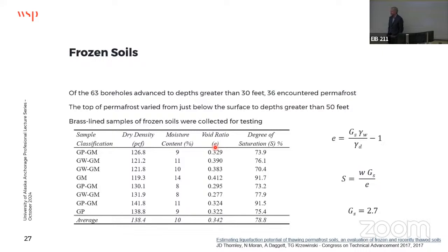So I'm kind of led to believe by your presentation that the main variable is the density of the soil. It sure seems like there are other variables that would apply to liquefaction that you can measure, things like clay content, grain size, friction angle. Don't those variables play into the liquefaction potential of the soil?